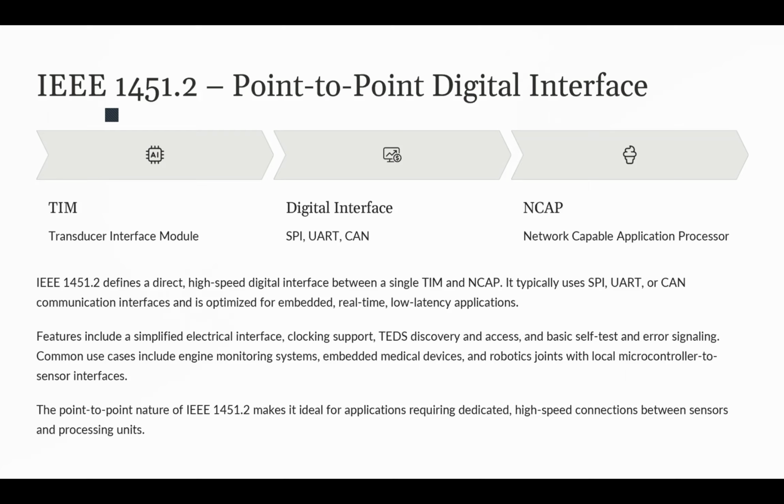Now, this standard includes commands for discovering and reading the TEDS from the TIM, which allows the NCAP to automatically identify and configure the connected transducer. It also provides optional support for synchronization between the TIM and NCAP, so we are able to have consistent sampling intervals and accurate time stamping.